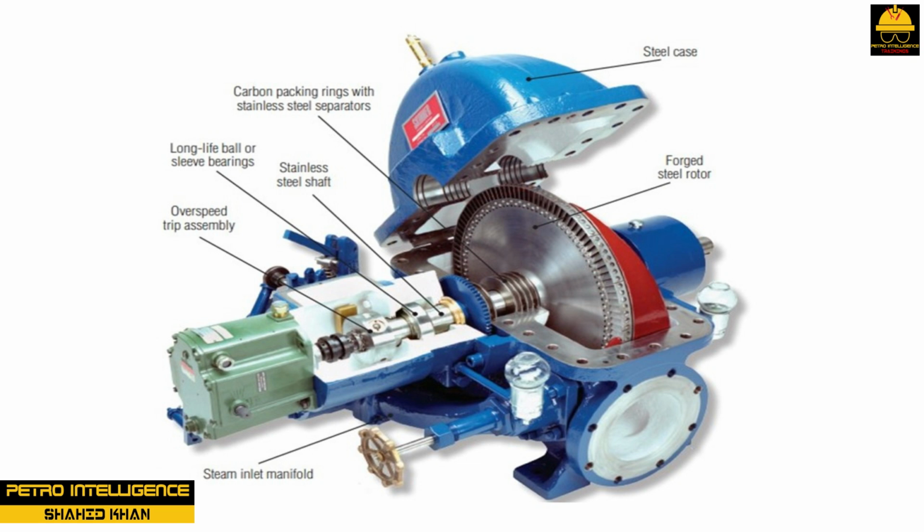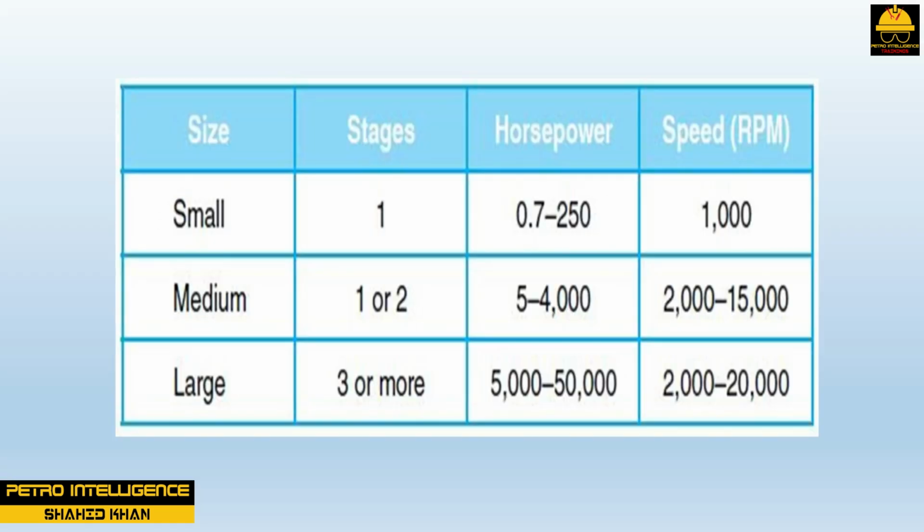In reaction turbines, steam is discharged from a nozzle mounted on the rotor. Movement is a reactive response to the release of steam from an internal source. In impulse turbines, steam from an external source acts on the rotor to create movement. Most plants use this design. Each of these designs can have one or more stages. This table lists the parameters of turbines.